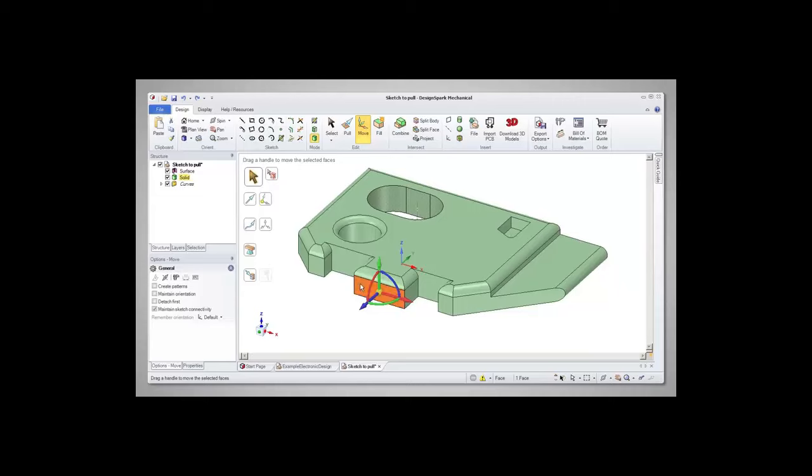The curved arrows on the Move anchor enable rotary adjustment of a feature. The same 3 steps apply as before. Select the feature, select the direction of rotation, and finally rotate it, either by dragging the anchor or by typing in an angle.